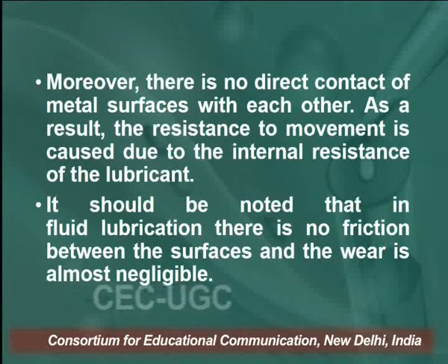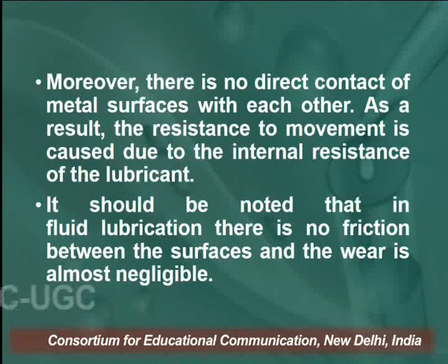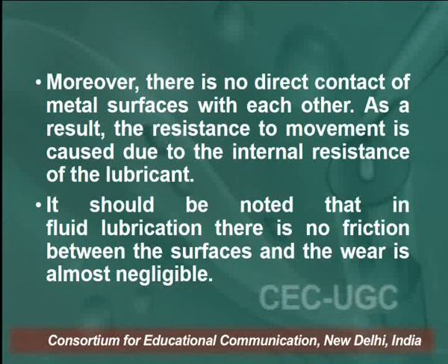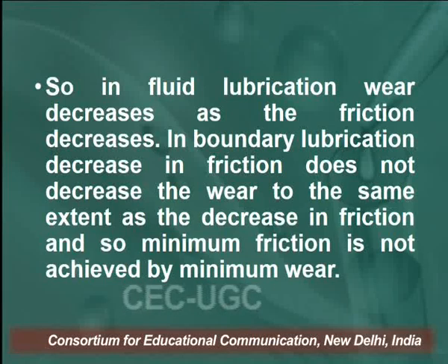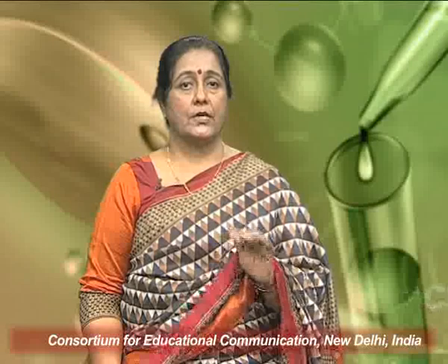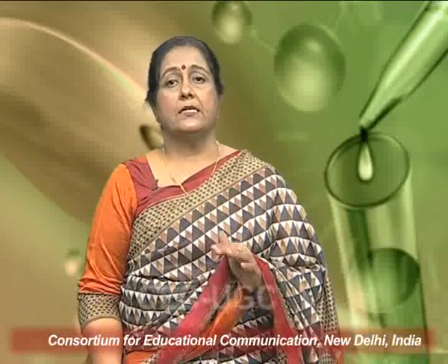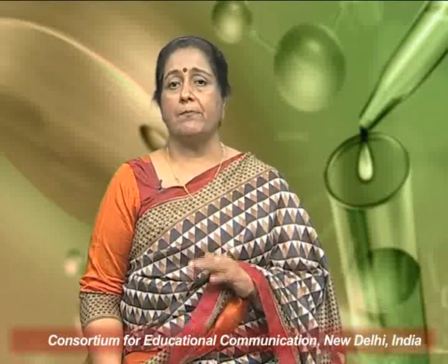As a result, the resistance to movement is caused due to the internal resistance of the lubricant. It should be noted that in fluid lubrication, there is no friction between the surfaces and the wear is almost negligible. So, in fluid lubrication, wear decreases as the friction decreases. In boundary lubrication, a decrease in friction does not decrease the wear to the same extent, so minimum friction is not achieved by minimum wear.